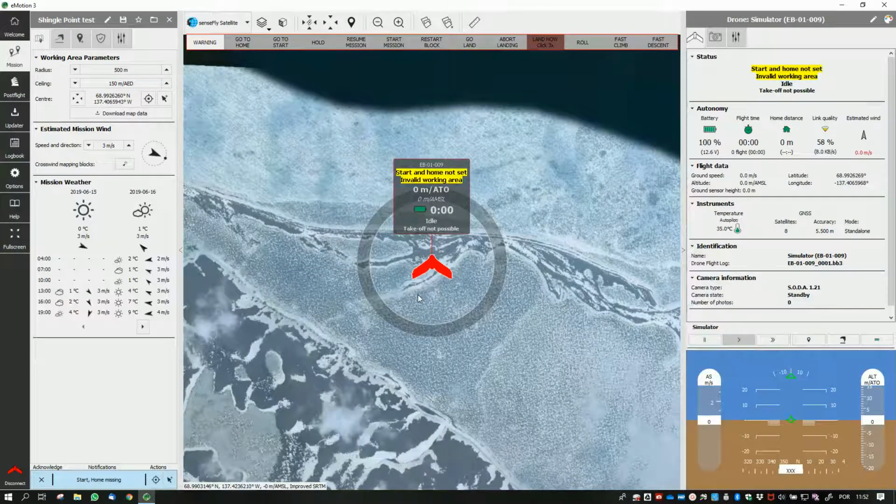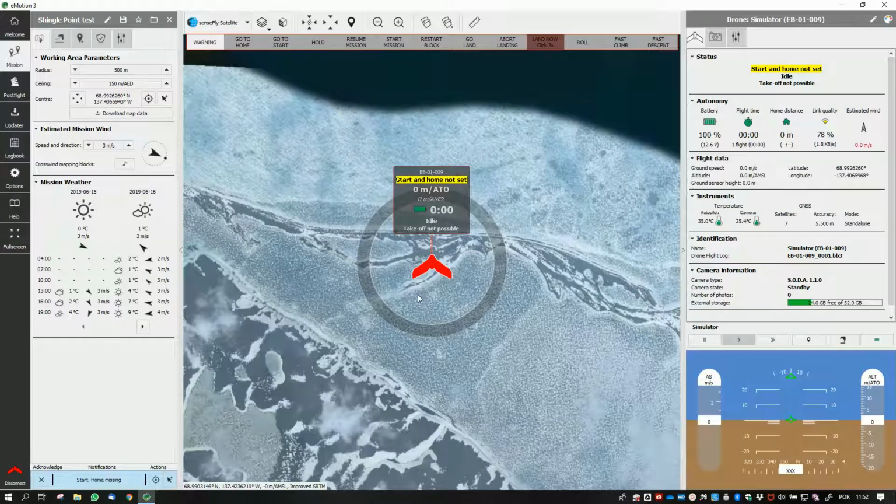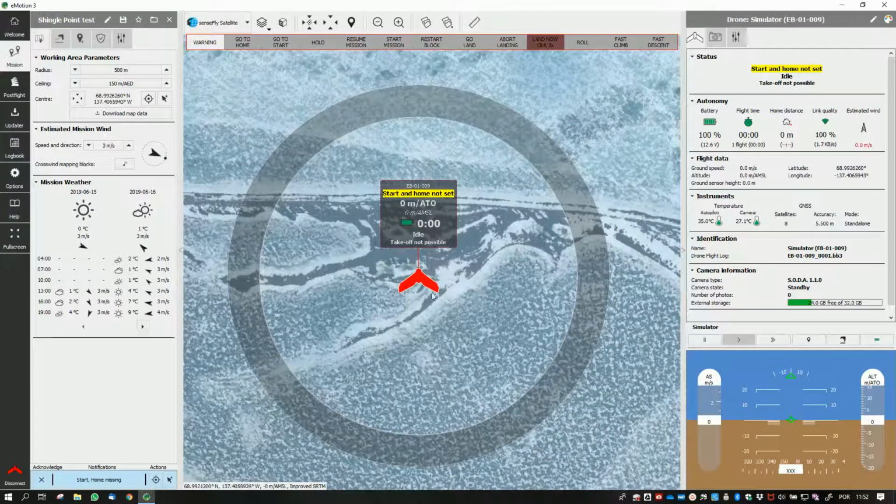Okay, and it has connected. Pre-flight checks completed. Whenever you have your drone with the battery on, it will locate the drone in the exact site where it is. So just be sure that the drone is pictured in the correct location, because it relates also to the accuracy of the GPS and if the GPS is working well or not in your drone.